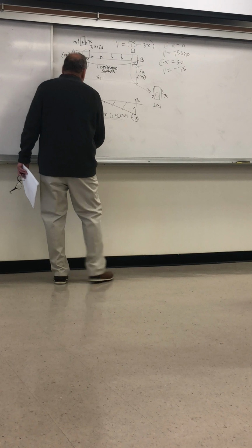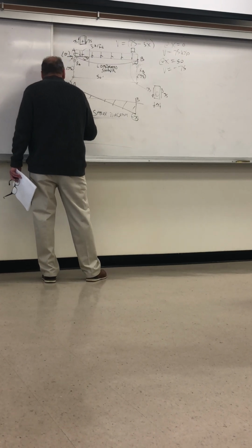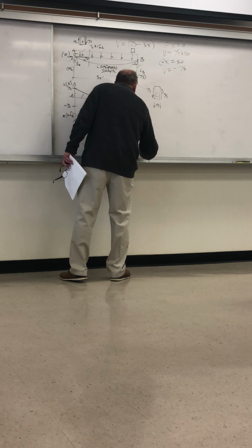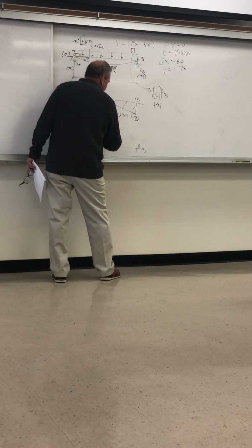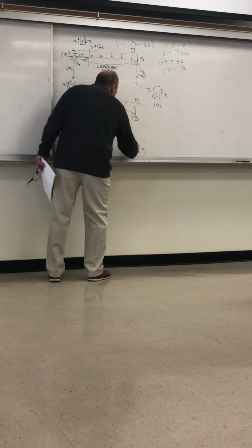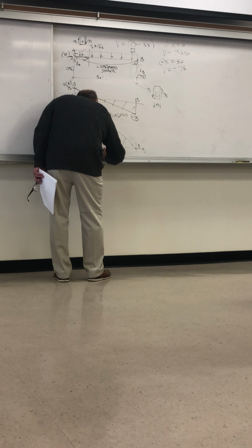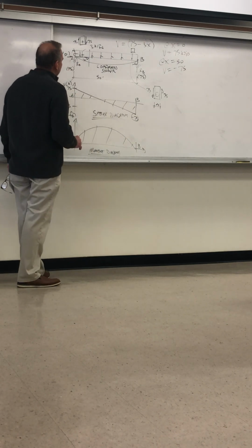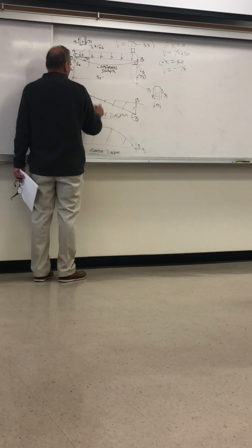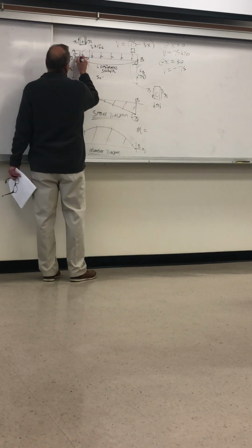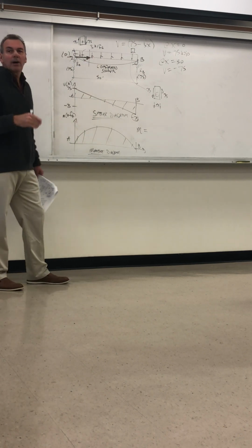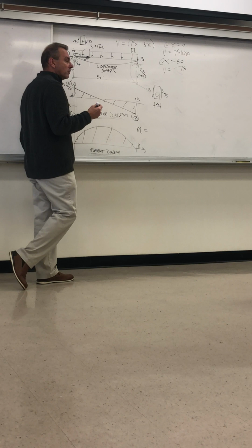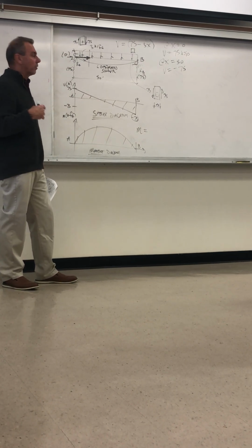And let's look at the moment diagram. It's going to look like this. Something like that, parabolic. Maximum in the middle. Moment diagram. We can write the moment expression. So here we have M. Again, this is as a function of x. So x is starting at the left and can continue all the way across. And the moment is a function of x at any location x all the way across. So this is the shear equation and the moment equation. They're both valid over the whole 50 feet.